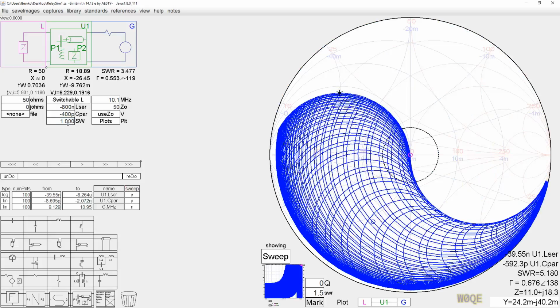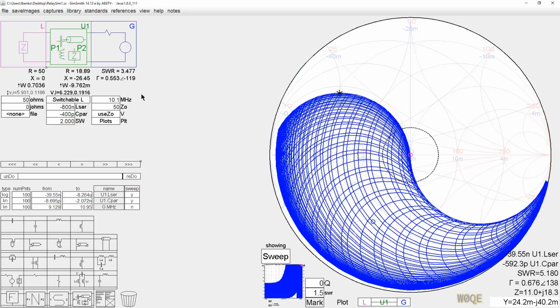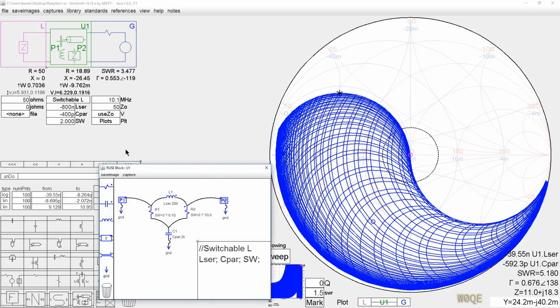It's more a configuration example to show you how you can use the relay switch to toggle the two networks. And you could make the complexity of this circuit as much as you wanted to. This could very easily be bands. These could be a band switch that would go across shorted sections of inductors. The inductors could be coupled together. I didn't talk about that in this video either, but you could couple the inductors. You could see the voltage across the switch contacts in a band switch.